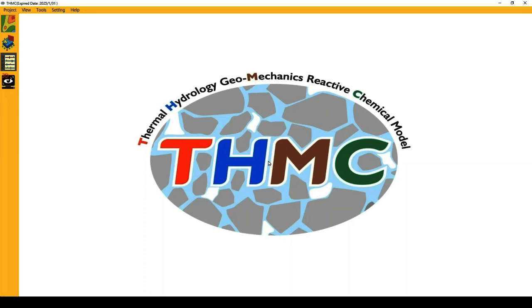The first screen is composed of 6 menus located at the top of the window, and 4 GUIs. The Site Conceptual Model Information GUI is a GUI that generates meshes using shapefiles produced from GIS and borehole data. The Geometry Mesh GUI allows for the manual configuration of the mesh and designates nodes, elements, and element sides for the spatial information of initial and boundary conditions.